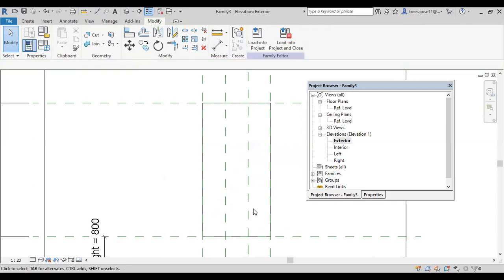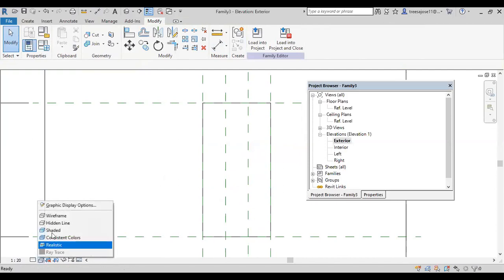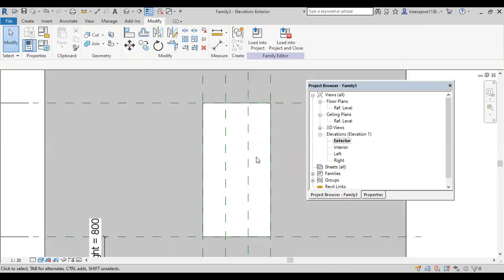Then you have to create a frame. In the case of windows and all, this is already open, no need for creating the opening. First you create the frame. If there is a structure and all, cut structure and all, you go to the sweep command. Otherwise, if you need that as rectangle only, go to the extrusion command. In the case of windows, you have to create a frame, panel, after that glass. Okay, that is the procedure.